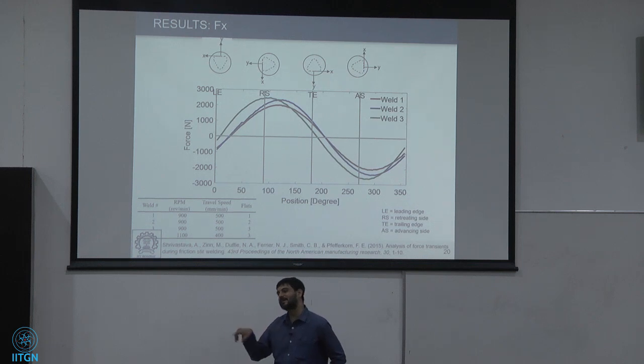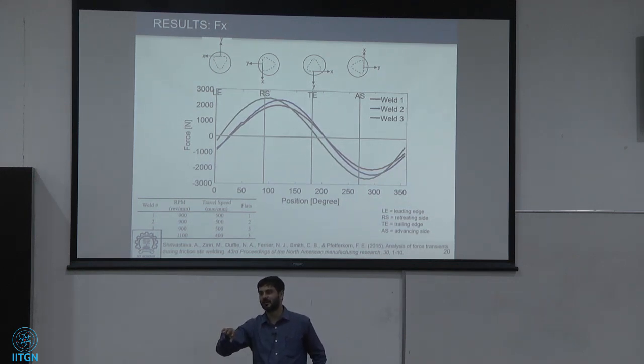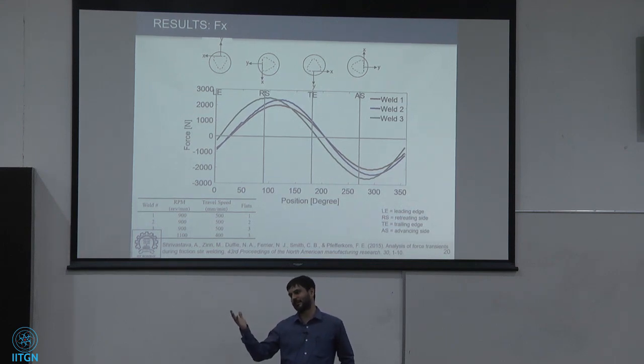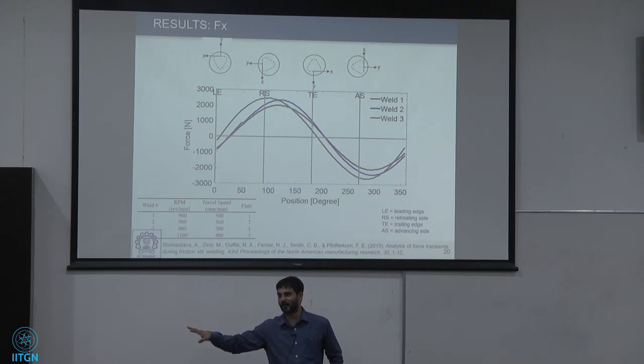So this was a completely separate setup which I developed later on. And here we went to a NI card which had a sampling frequency of up to 1 megahertz. So sampling frequency was very, very high, and it had a built-in filter feature which introduced lag or leads, if I remember right, to the order of nanoseconds. I mean, if it's inbuilt, then it is consistent throughout. Exactly. So it takes care of any such lead and lag, the card itself. So there was no need to do any post filtration at the LabVIEW or at any interface which we were using at that end.